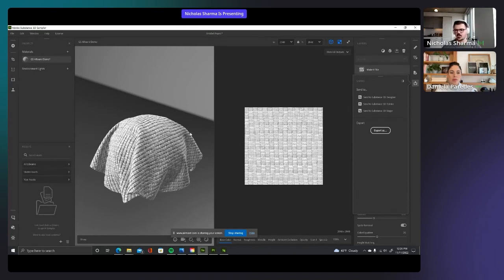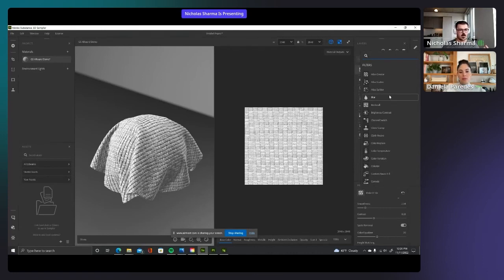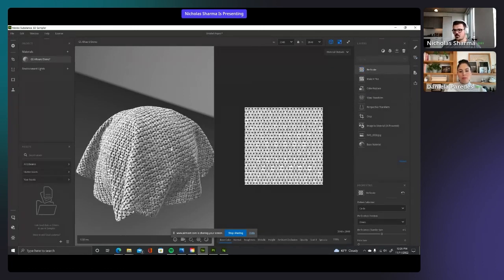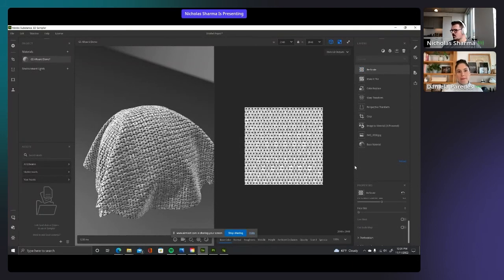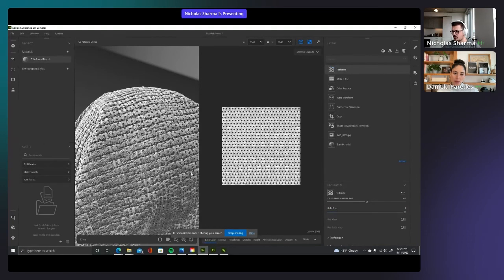What's nice about Sampler, and I didn't get much of a chance to showcase it, is this: let's say you have a material that you found online, or grabbed from scratch, and you want the ability to make it parametric, to change things over time. So maybe I want to add perforations and patterns into this material. In Sampler, maybe I want to change the hole size because I don't know exactly how big or tight I want the holes to be. You can click on this little pin icon, called exposing the parameter. So when you bring this material into Painter, you can make those adjustments later on.